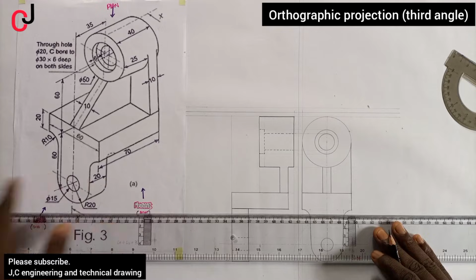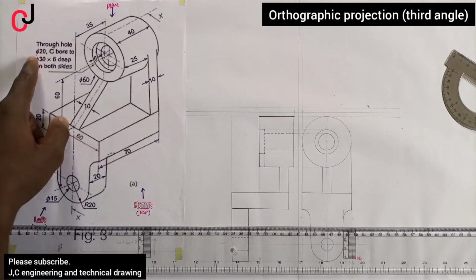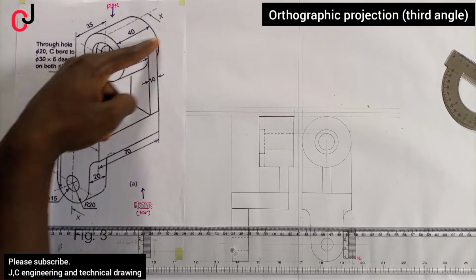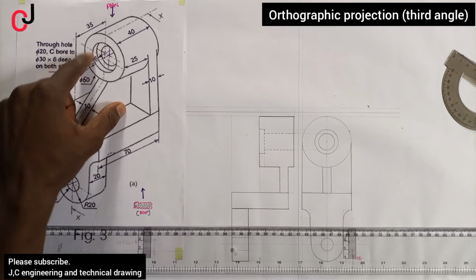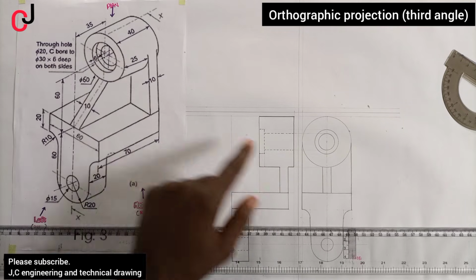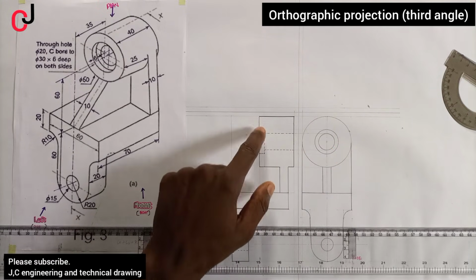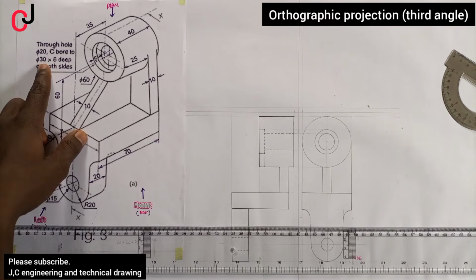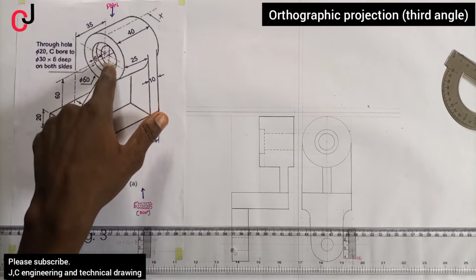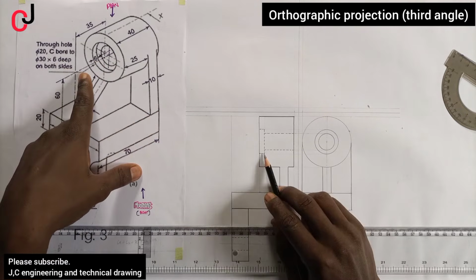Now this shows that there's a passage of diameter 20, a hole passing through this from our side view, which is 20 diameter, and then this here indicates that there's 30 diameter here, that is this, and then the last one, which is 60 diameter, which is this, showing that the 30 diameter of this circle is 6 deep, which is this 6 millimeter deep.